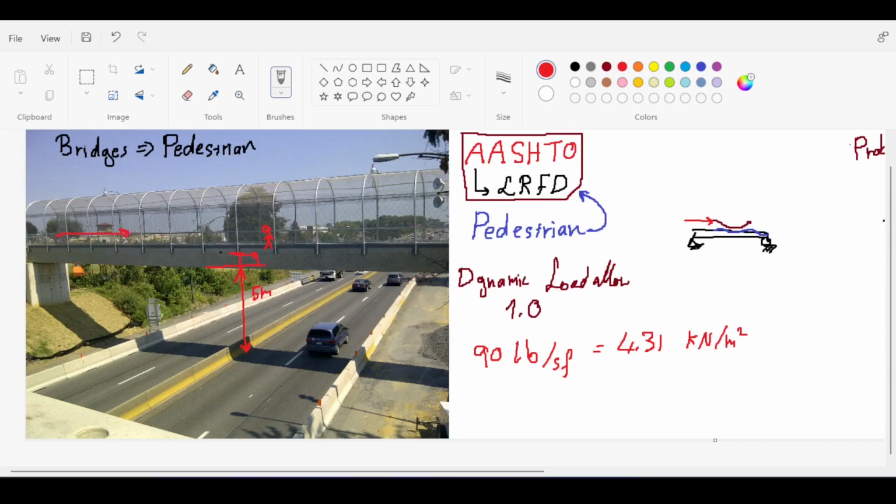Why do you need to take those into account? Because when you take wind loads into account, first of all, your beam that is carrying the bridge, this pre-stressed beam, is going to be under biaxial bending, because there is one axis bending from the gravity loads and one axis bending from the horizontal loads. That's problem number one. Problem number two is that the piers that carry the bridge are also going to have biaxial bending. One bending is due to the bridge, of course, if you assume a fixed connection. If you don't, then there is no bending. And the other is due to lateral bending.